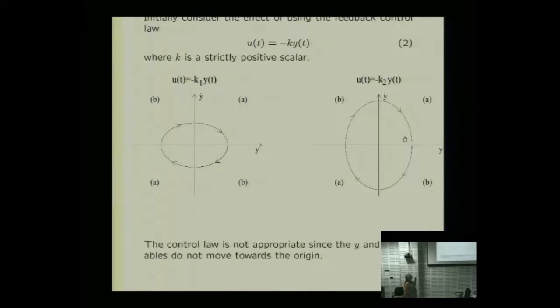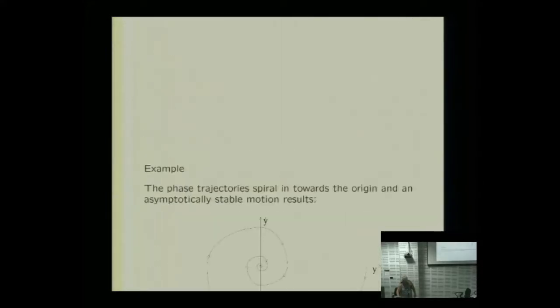If we look at the phase portrait on the left-hand side, we can see that in this quadrant here marked B, if I start on the y-axis here and I move round, again the distance decreases. So I get closer to the origin. So a simple look at variable structure controllers could be to say, well, what happens if I have some control systems that have good parts and bad parts? And I try and build a system which takes the good parts of one and replaces its bad parts with good parts from another controller. And doing that with this simple example is